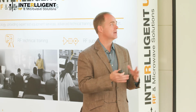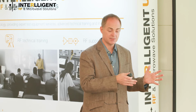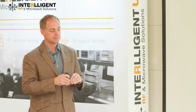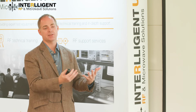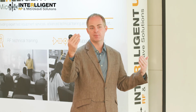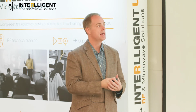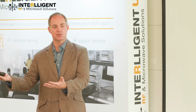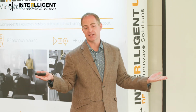So there's a lot of ways that you could actually model these things. We tend to use a compact model, which we can use because it's a self-contained model and it can be extrapolated. So a lot of the other device models that are prevalent out there are based on direct fitting of measured results, which is excellent if you have the specific device that you're interested in, and you know that you can actually measure to the range of environmental and use conditions that you're going to see. That's not always the case, particularly as a foundry. We don't actually know the application space that our customers are going to use, so we need something that can actually be used in any environment.